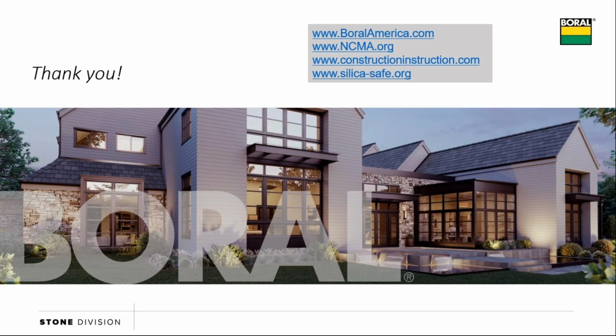Now you're still going to need to keep grade down because you don't want to cover that up and have water wicking up into the wall system or give easy access for bugs. But Chris, correct me if I'm wrong, the way I would read that is you would still need to terminate with a weep screed, but could bring your stone down to within a half an inch. I agree. Yeah, your key question or your key point there is, where is the earth or where is the mulch still? Yep.